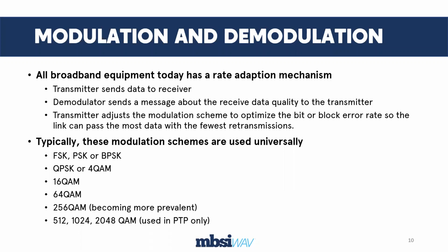The one thing you need to remember about all this, and I've got some tables in the worksheet that we're about to look at, has some minimum signal to noise ratio requirements to be able to decode that particular level. Sometime I'll do another session like this on modulation itself and what that actually means. But for the case of link budget here, we just need to know that the higher the level of modulation that we want to decode, the more signal above the noise we need.